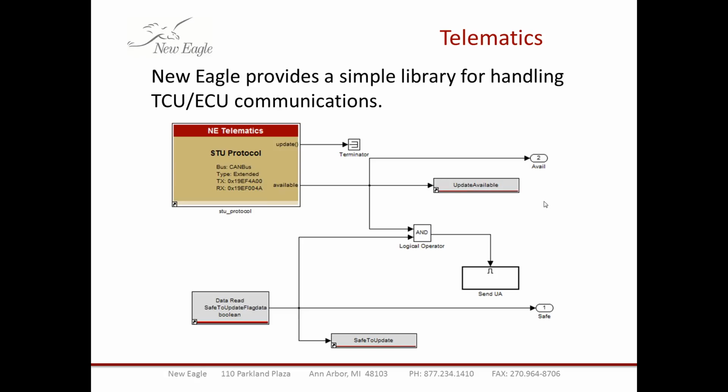In order to facilitate that, we provide a simple Simulink library for handling the CAN protocol between the TCU and the ECU. It's just a couple of blocks, one to notify the application that an update is available, and another one that notifies the TCU that the module has decided that it is safe to update.